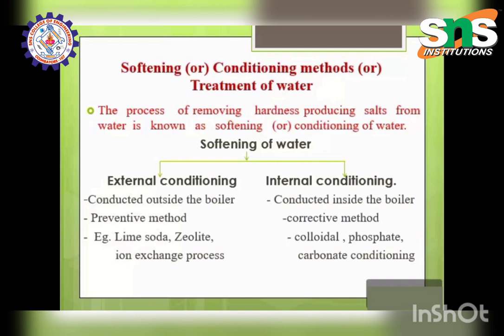The process is carried out by using ion exchange resins, which are long chain, cross-linked, insoluble organic polymers with a microporous structure. The functional groups attached to the chains are responsible for the ion exchanging properties. There are two exchangers, that is cation exchanger and anion exchanger. The cations are removed in the cation exchanger and the anions are removed in the anion exchanger.